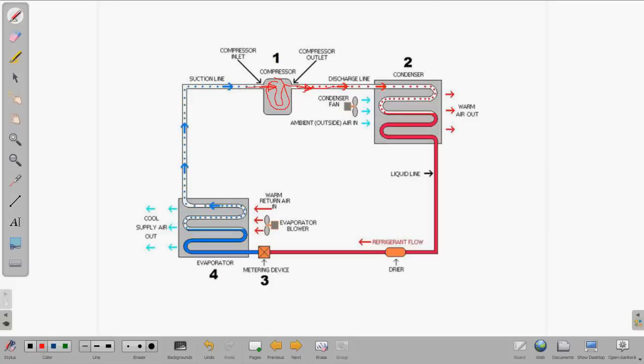But we still have our hot gas coming out of the compressor, and what happens here is the refrigerant runs through this condenser fairly quickly, so as it comes out of the condenser, it is still somewhat in the saturated state coming out of the condensing unit, and may not get subcooled until it gets partially down the refrigeration line set.